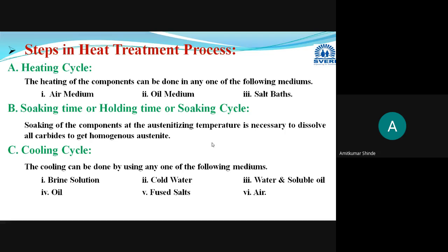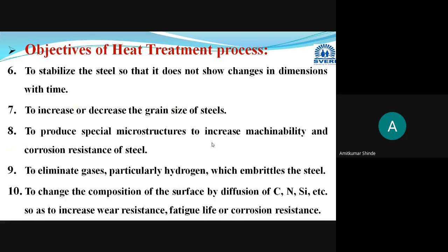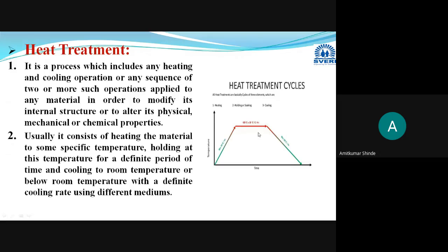Okay, this is related to the heating cycle, and these are the different mediums that can be applied for it. The next is the soaking time or holding time, or soaking cycle. In the first step, we are heating the component to a specific temperature, and after reaching that temperature, we are keeping it constant, or holding that component at that constant temperature for a definite period of time. That will be termed as the soaking time or holding time.